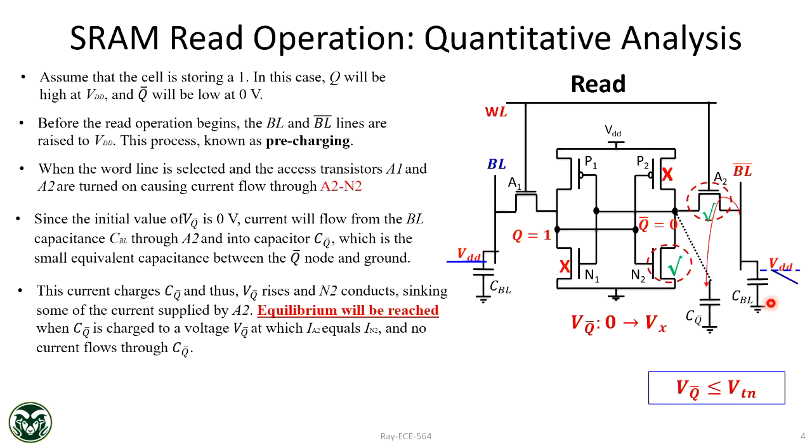Questions, comments so far? Make sense? Why does read have to be slow? Because you have to rely on a big bit line capacitor to discharge.